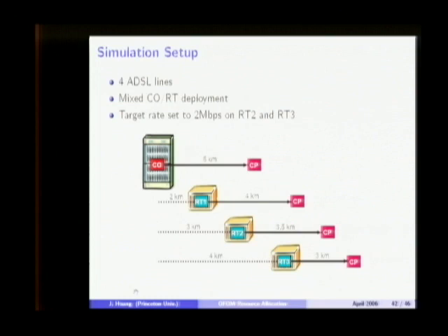But maybe. I see. So let me explain more. So first of all, these guys just associate a W for themselves, right? And they do the local optimization, ASP algorithm. And they look at the rate. For example, this guy got a 1.5, this guy got a 1.5. And these 2 will just increase their W and re-optimize. And because the interference changes, everybody will re-optimize. And if that doesn't work, they will further increase their W. And if it achieves more than 2 megabps, it will decrease. So there should be a couple of iterations.